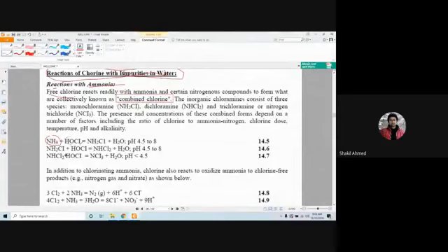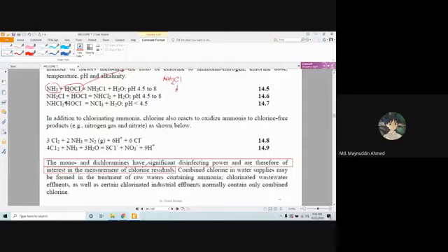So this ammonia reacts with the HOCl, that is free chlorine, to give you, look at this, one H is gone out, NH2, and one chlorine from here comes in. So NH2Cl. How many chlorine is there, guys? One. So that is called monochloramine. Mono means what? One, right? Yes, sir. It's called monochloramine.